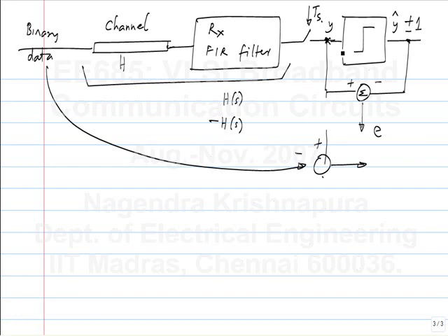No. See, let's say you take some random bit pattern which has lots of combinations of zeros and ones. Now, this is a linear filter. So, if it is giving you 0 error for that, any other bit pattern can be realized as a linear combination of other patterns, because of linearity. So, what you describe won't happen. It's not that it will give you 0 errors for certain patterns and then non-zero error for some other patterns. Comparator is not linear, but we are making sure that at this point we are getting plus ones and minus ones at the sampling instant.